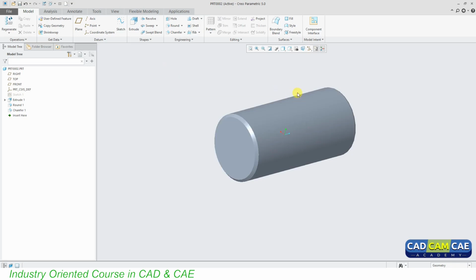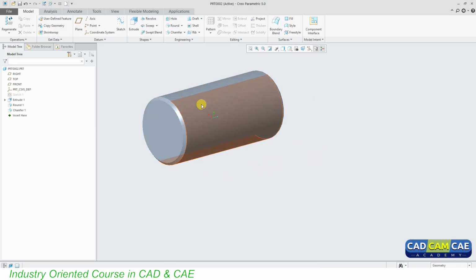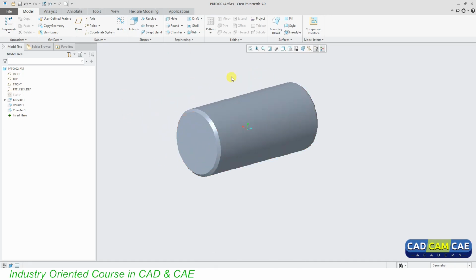Like let's say someone has to create cylinders of different shapes, different dimensions repetitively, which need to be used for assembling purposes. For that case, you can create the UDF feature, and you can just read that feature whenever we want to create this particular object for the subsequent assembly or during the modeling.